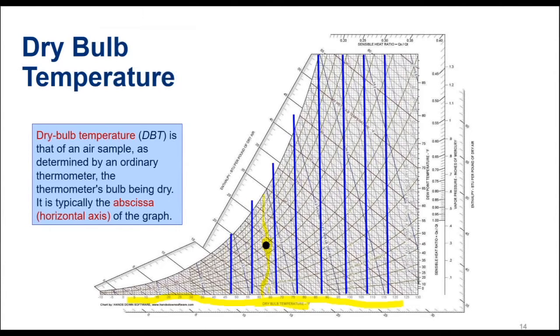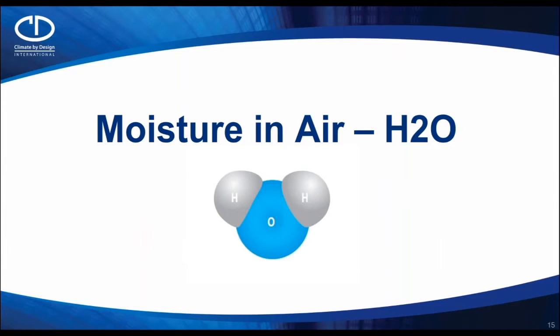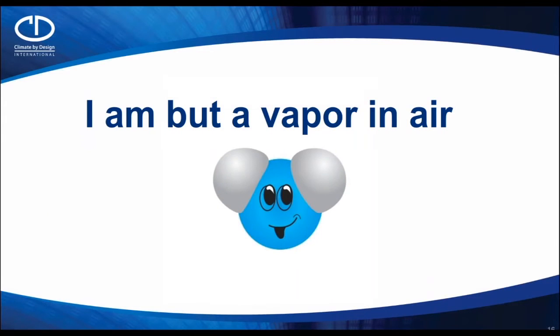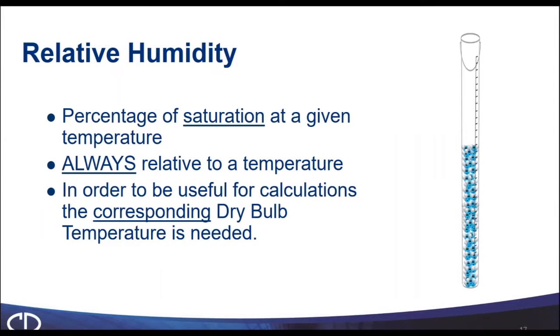We're going to move our conversation to moisture in air. H2O, 2 hydrogens, 1 oxygen. It's nothing but a vapor as we see it in air. The most common moisture measurement that we relate to or hear the most is probably relative humidity. It is a percentage of saturation at any given temperature. It's always going to be